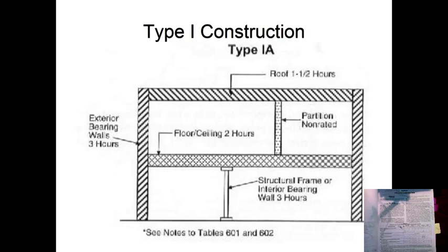How do you put all of these different materials together? That's an assembly that you see here. And then it talks about roof construction. You can see here the roof has to have 1.5 hours if it's non-protected, and 1 hour if it's protected. But always notice these little letters down beside or back behind them.